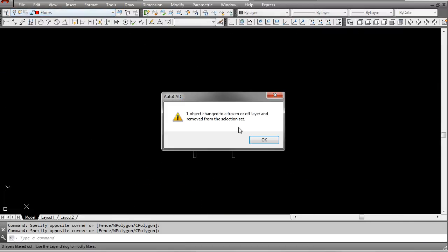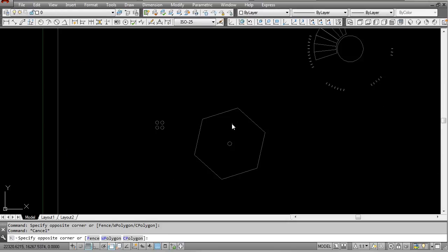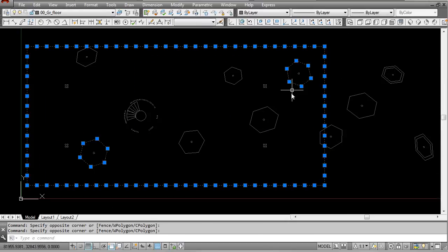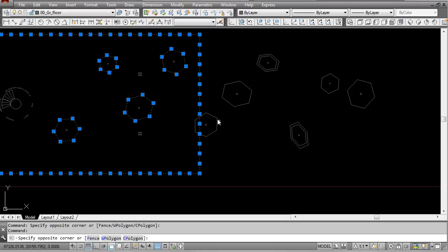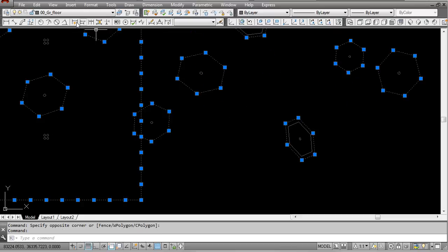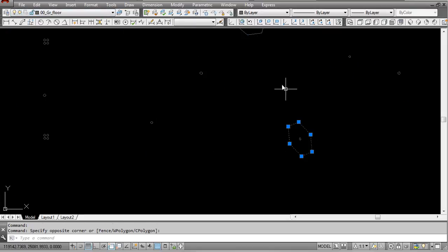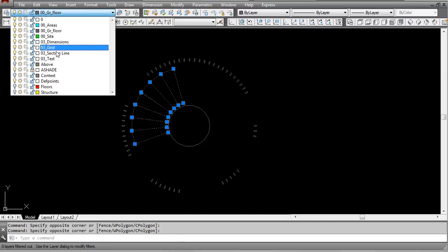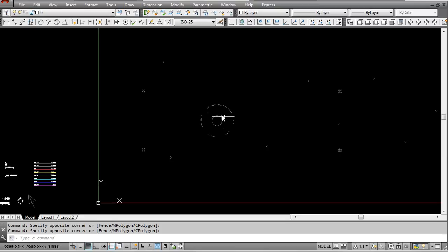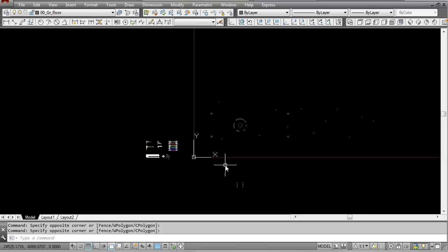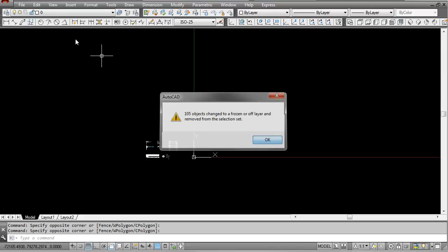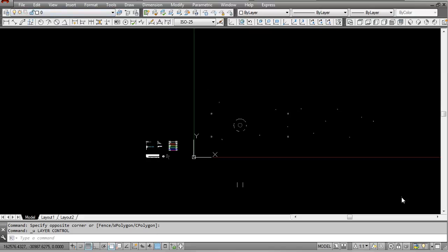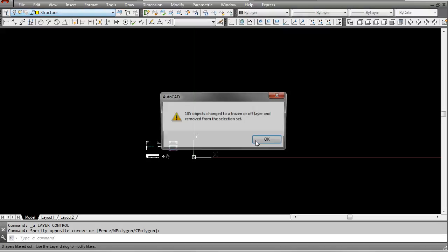This is going to go onto the floor layer, and I'm now going to select everything that's above, which is going to be the actual pavilion or the expo floor, which is above the entire ground floor, as well as all of these canopies, which are going to be above too. So that goes to the above layer. This will also go to the floor layer, and let's also assign these stairs to the floor layer. So that's going to go there, and then everything else is going to be layered as structure. So I'm just going to repeat that process, structure layer.